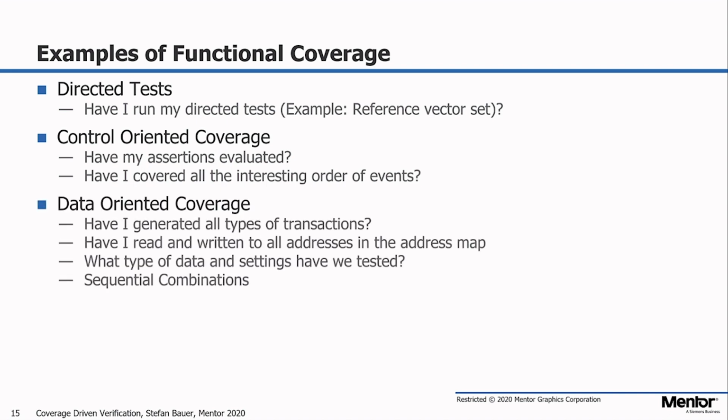The last one is data-oriented coverage, where I answer questions like, have I generated all types of transactions? Have I read and written to all addresses in the address map? What type of data and settings have we tested? And you can also cover sequential combinations. In my next slides, I want to go through the last two coverage types.